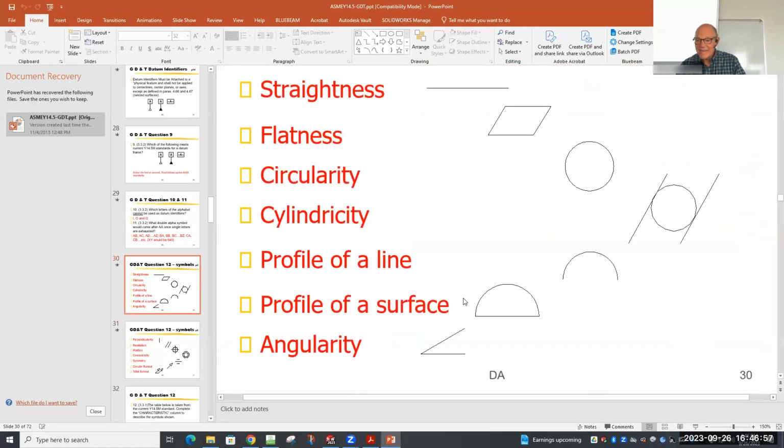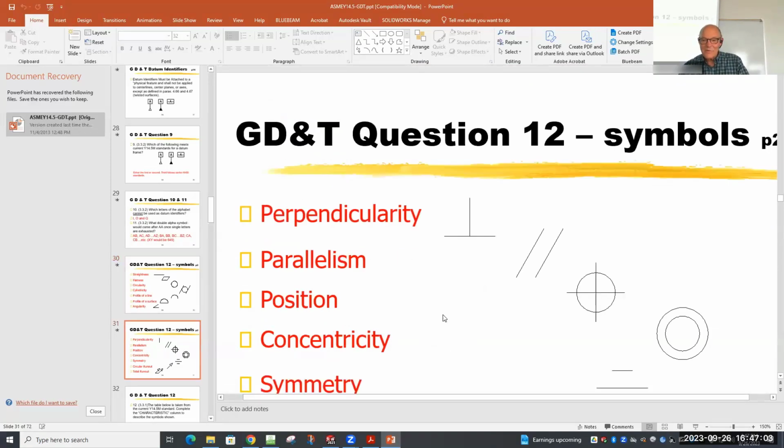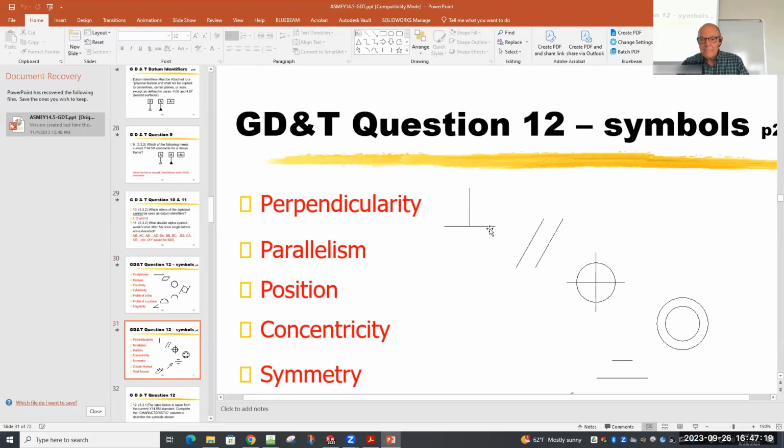And then angularity. Now, angularity by itself should control everything, but angularity is a separate control from perpendicularity and parallelism. They're actually all angularity. One's 90 and one's 0. So you could get rid of perpendicularity and parallelism. In my opinion, if I was setting this up, I would dump four of these things and just allow others that are already there to take a new count.